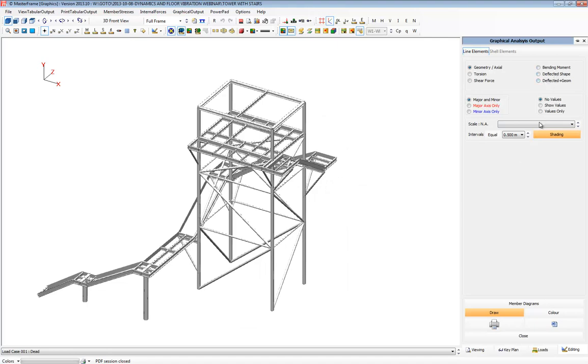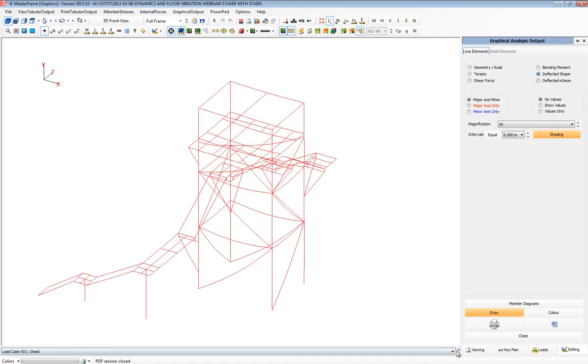And I want to show you the deflected shape first. This is without any dynamic loads being considered, it's just under the self-weight of the structure. We can see the deflection of it. Now, we take the dynamic load caused by that machine, at the worst time for this structure, that causes the worst displacement in the y direction. We now have a snapshot, and we've added this so we can see that straight away the floor is actually deflecting a lot more when the dynamic loads have been accounted for.